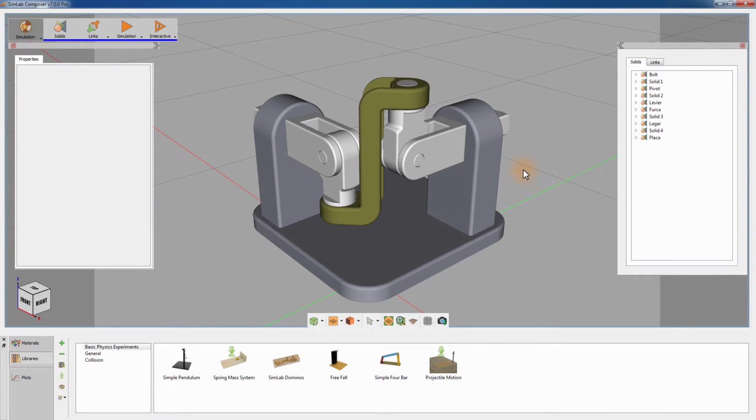Let's quickly go over the mechanism of this joint. The two ends of the joint are fixed in place by a socket that would allow them to rotate in place. The rotating rod is then connected to a small shaft through a pin, and the pin is connected to a lever that serves as a transmitter between the two ends of the mechanism.